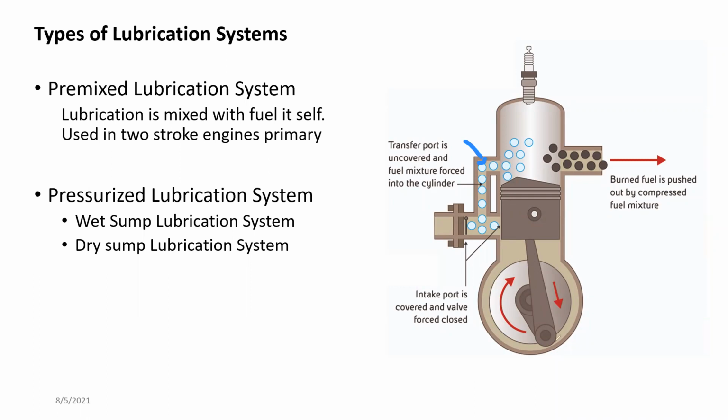In other applications, the pressurized lubrication system is very rarely used. Since there is one cylinder, there's no point of having hydrodynamic lubrication for the piston or the crankshaft itself. Also, in these cases, we can just use a ball bearing crankshaft.